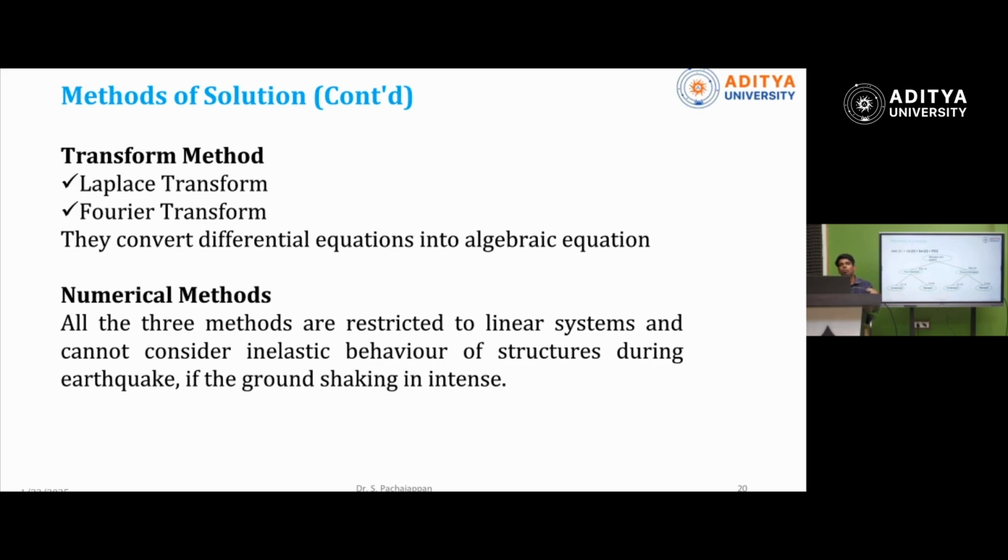If you come to forced vibration, there also damped forced vibration is there, and undamped forced vibration is there. So what is forced vibration? A load will be there at the free end, continuously pushing the system up and down. That is a forced vibration. Damping also will be there; that is the damped forced vibration. Forcing function is there, but damping is not there; that is the undamped forced vibration. So this is the whole classification of vibration systems. There are no vibrations more than this.